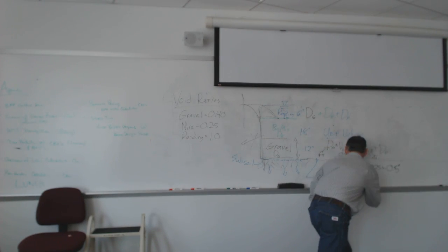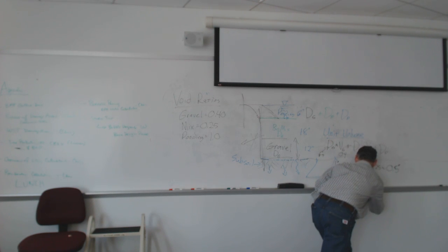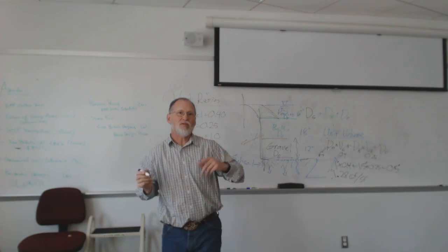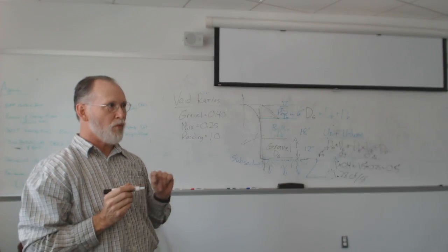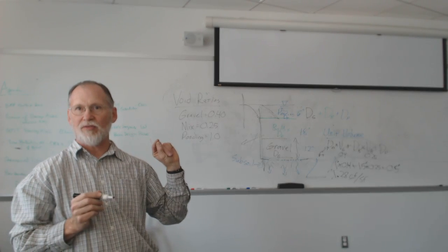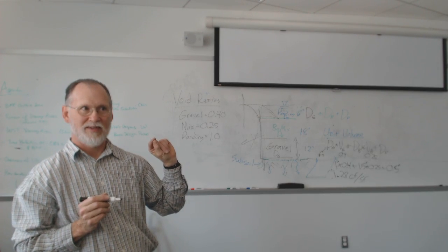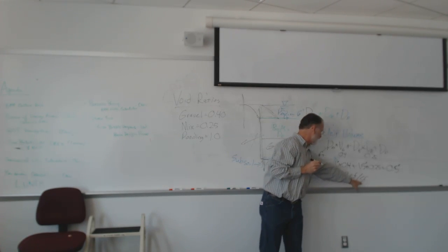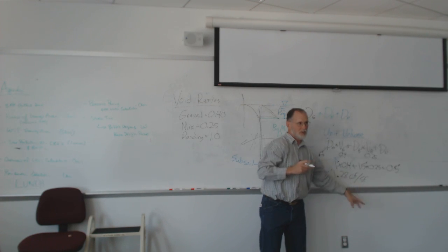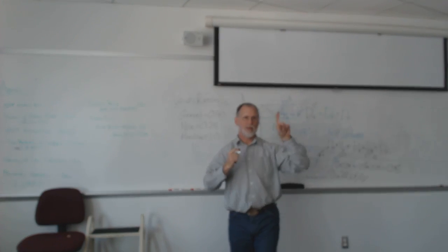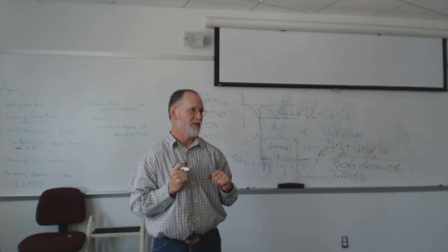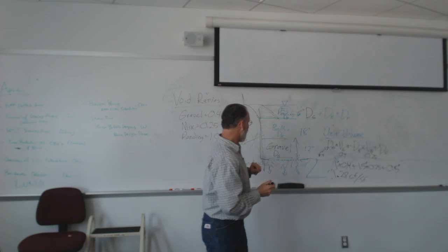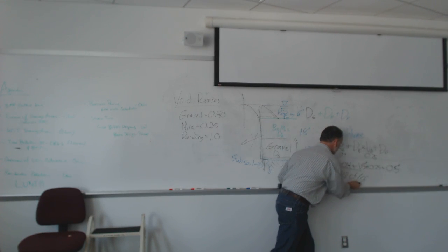So we can hold a little over 1.25 cubic feet of water for every square foot of rain garden surface area, because this unit is for a 1 foot footprint, and it's how much we hold as we use these different mixes. So that is our unit volume down there. Can everybody see where it came from?